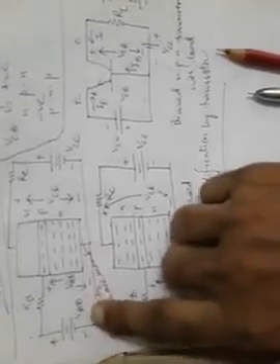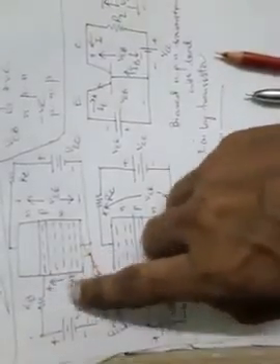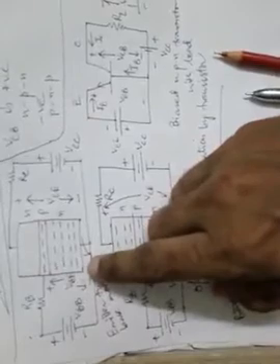When the base emitter junction is forward biased, the electrons from the emitter will not immediately move into the base until the base emitter diode is getting a higher potential from VBB than VBE, because VBE, we know, is 0.7 volt for a silicon diode.